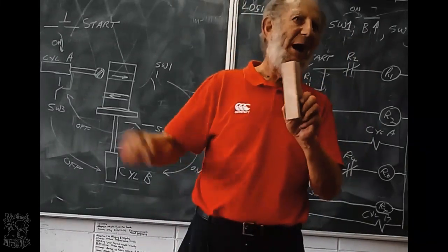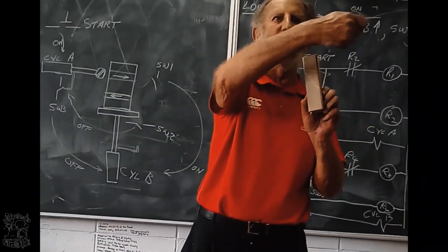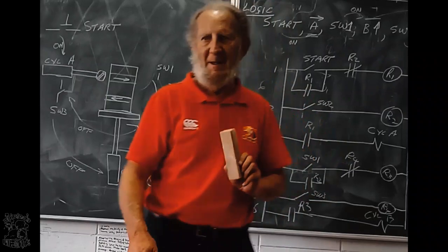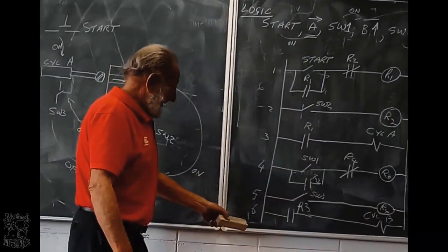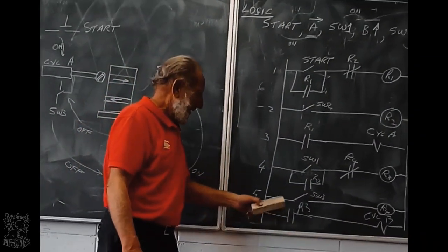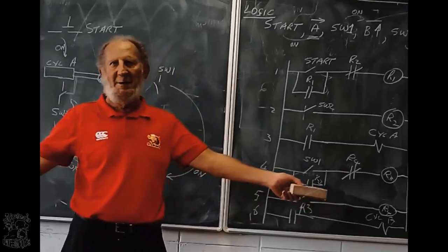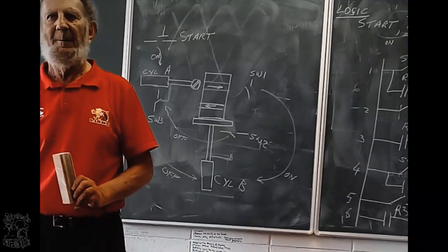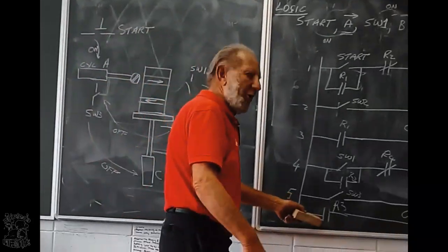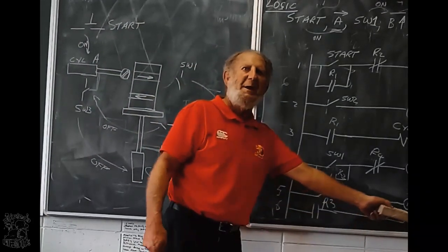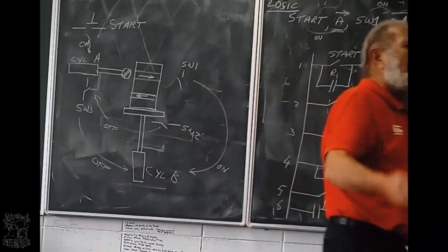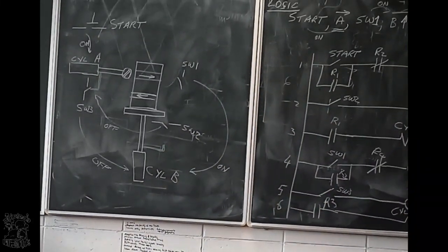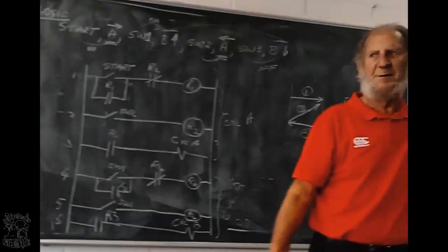It will cut the first groove, and then it will stop, B cannot go up. Line 6A. It will stay open, cylinder B cannot start. We'll cut the first groove, and then it will stop. If this stays closed all the time, B has got power all the time, it cannot come back. It will complete both jobs, but B will stay on top, it's not going to come back.